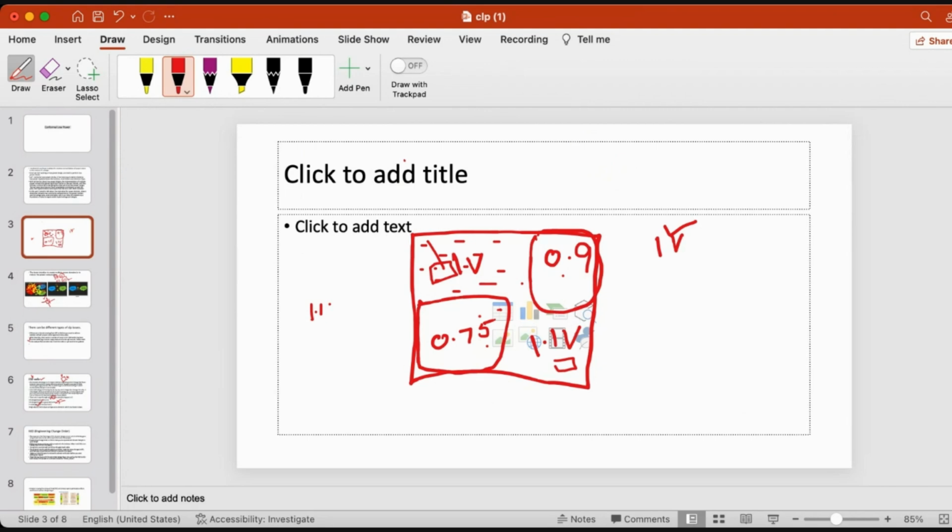This has to be added during your floor plan itself. ESD is like a macro, like an analog macro. So you have to add ESD during the floor plan, and then you have to place your standard cells.